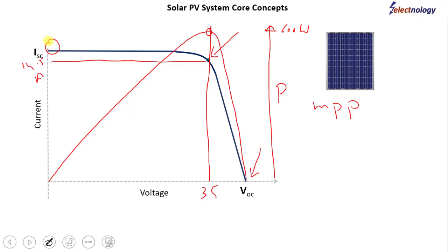So the PV module shall be operating over this point, which is the MPP point, maximum power point, and the inverter which has this feature to operate the PV module at this point has a particular algorithm or equipment or devices inside it, which is called MPPT, maximum power point tracking, meaning they are always running an algorithm inside the inverter to operate the PV module on this point to maximize the power supply.